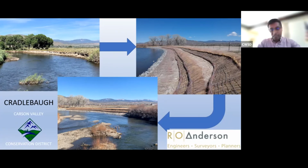It's not that steep. And this is just downstream of Cradle Bar Bridge. So Mitch, we gave you a lot of conveyance, so you need to go and update your models, your mapping. Basically we provide a lot of conveyance around this area, which slows velocity down and hopefully helps the river banks at this location.